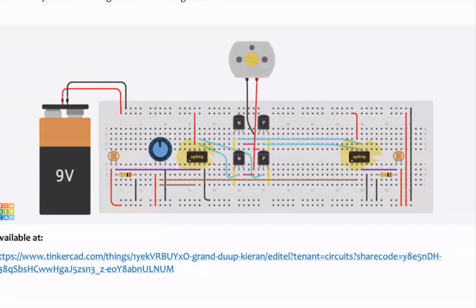We also know from the previous lab that you have these LDRs here, two of them, one on each side of the solar tracker. Because there's an inverse relationship between the light intensity and the resistance, when the light intensity increases, the resistance decreases, correct?